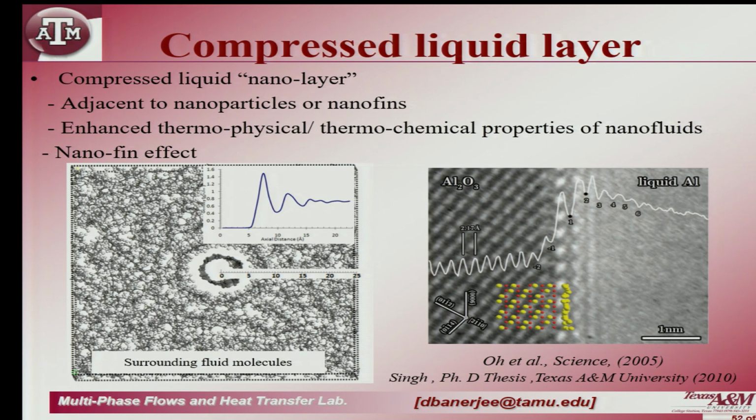FCC, BCC, I am saying it in loose terms, but you understand the concept I am getting at, right. So, the crystal structure of your container now starts affecting the crystal structure of your liquid inside it, and so therefore, the properties of the liquid start changing depending on the container you are putting it in.